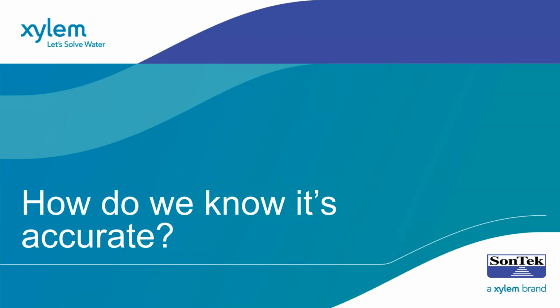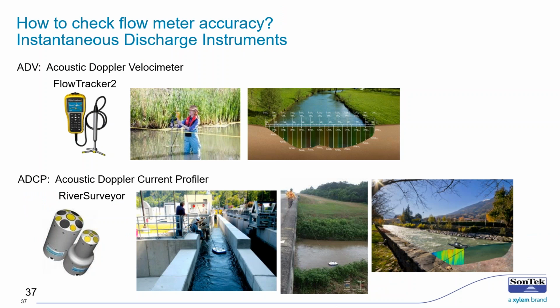Thanks, Diego. So the last question we haven't answered yet is, how do we know it's accurate? Any flow meter that you put in the water, of course you want to know, right? The quick answer, and we could do a whole different webinar on this, is instantaneous discharge measurements. And if you have no other reference, or the whole point is that maybe you're questioning your reference, or you have two references that are differing, this is the method you would use.